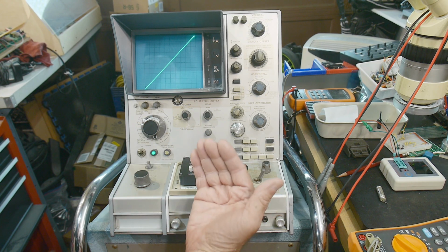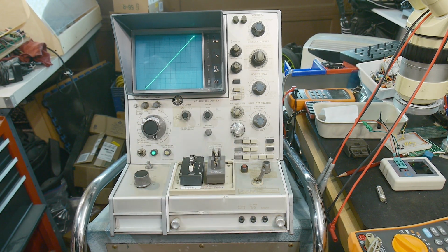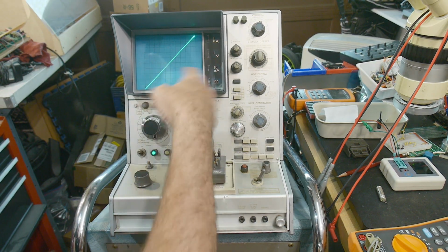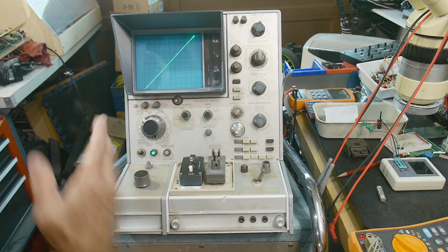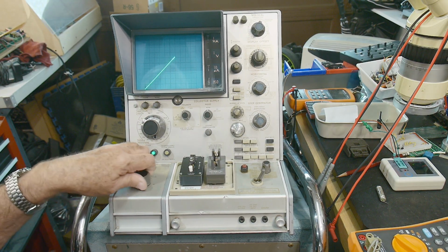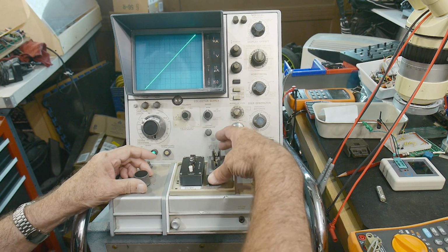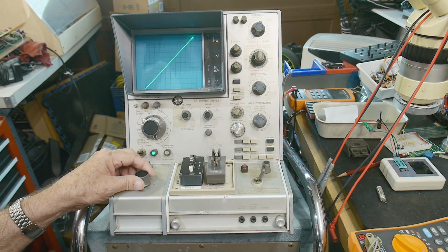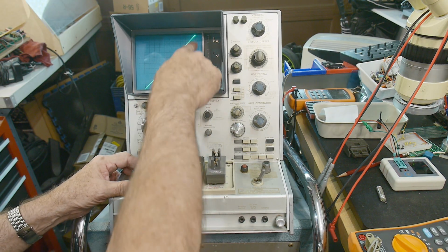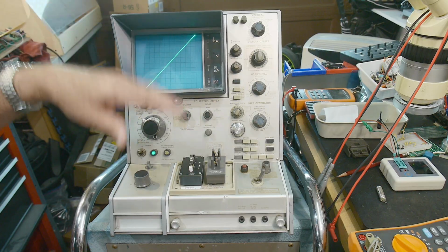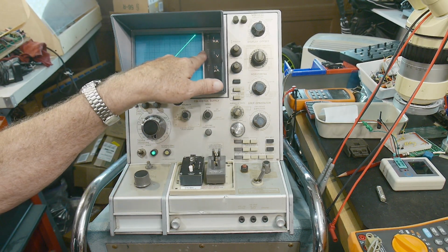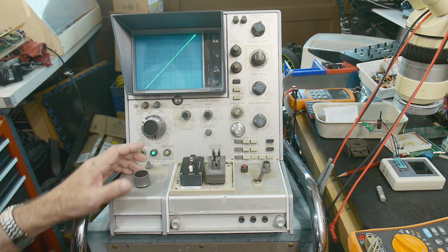And a resistor then is volts divided by current. Volts divided by current is a ratio, and rise over run is a ratio, right? It's a slope. And this slope is exactly what a 1,000 ohm resistor would do, right? If I have 1 volt per division, so I have 10 volts here, and I have 1 milliamp per division, I have 10 milliamps.